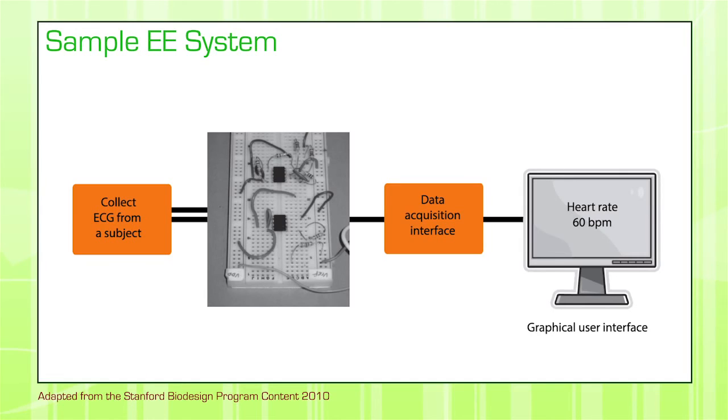So is there going to be a data acquisition system in order to store the data or process that? What type of monitor am I going to use? What type of interface is the user going to have in order to know the important things of the information that you're getting from the electroencephalogram? This is something important to describe early on in your prototypes, even though it could only be on paper.